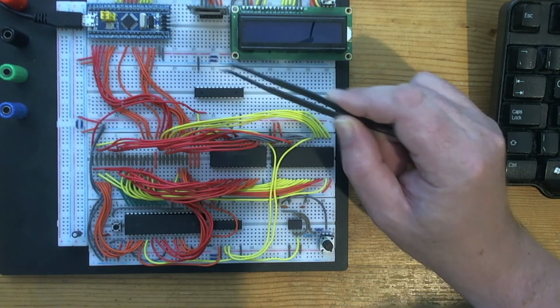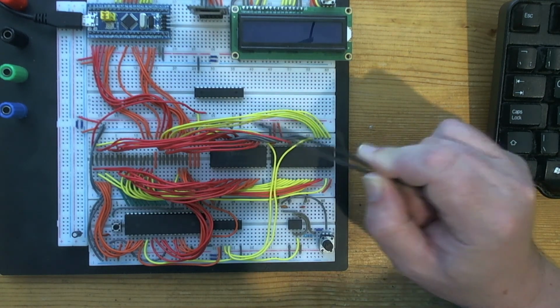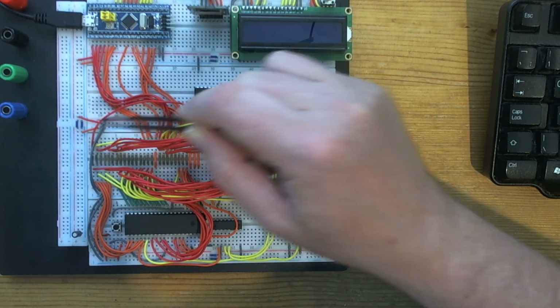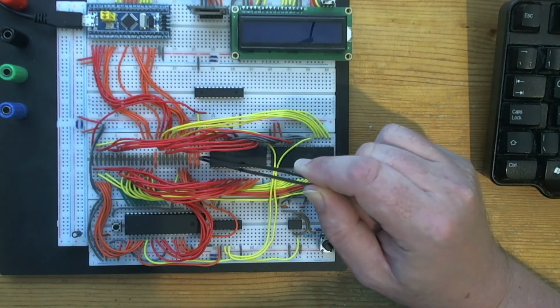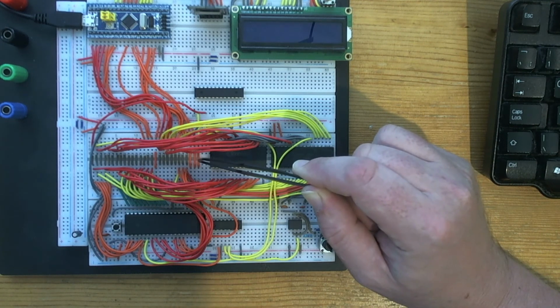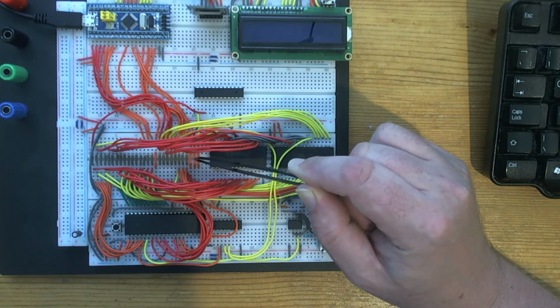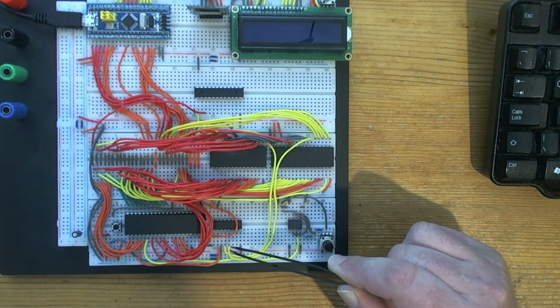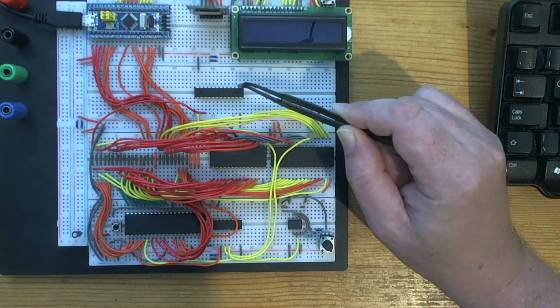I've given it power, and I've given it ground, and I've already wired up A15, which is going to the makeshift address bus over here. This is A15, and I've wired up memory request here, because that wasn't previously there. So I've got 4 control lines here. I think that's IO request, one of those is read and write, and then that's memory request. So the next step is to take these address lines and just move them up to here and here.